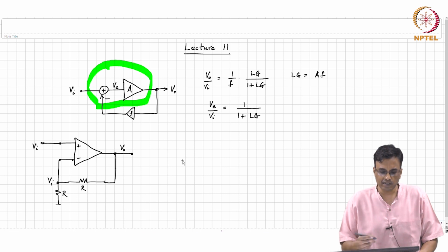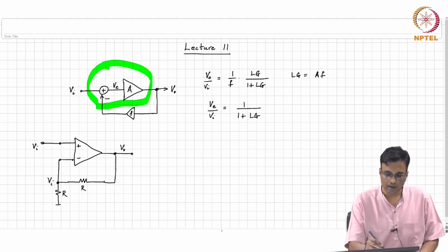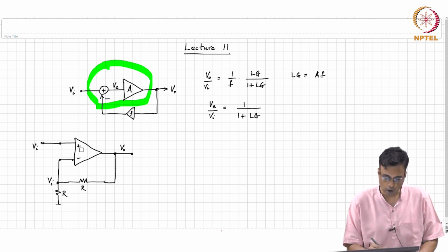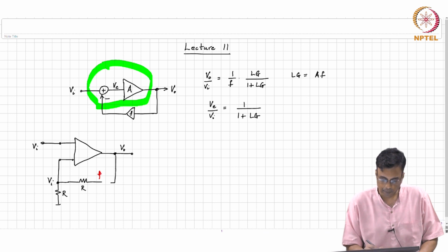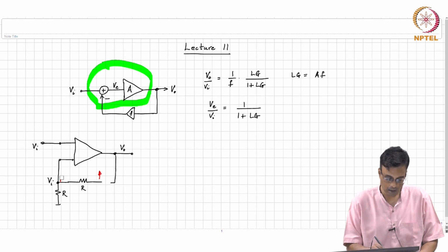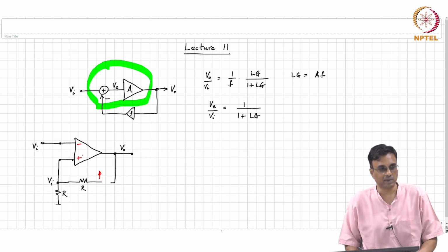Now, let us say you had never seen this circuit before and you wanted to figure out what the signs of the op amp must be. You did not know the signs. So, what do you do? You break the loop somewhere and you yank one side of the loop up here. What happens to this node here? What direction does it go? Let us assume some random signs like that.